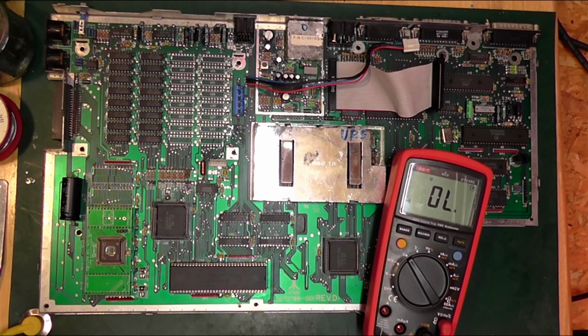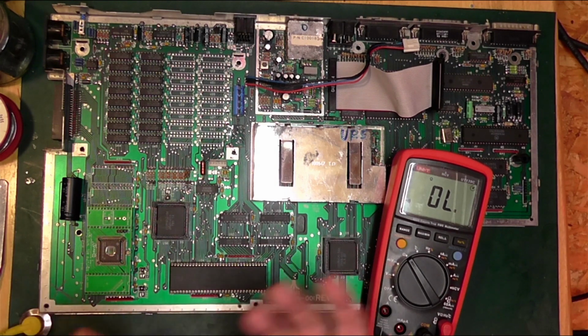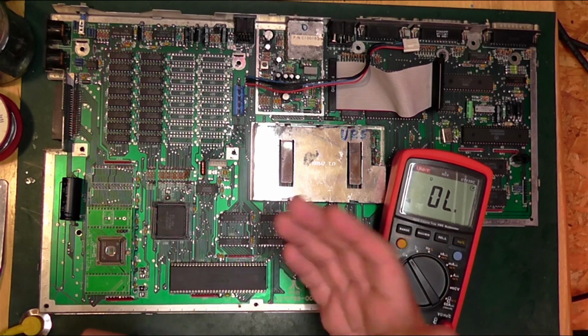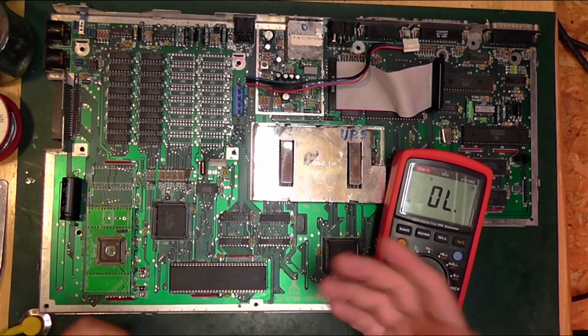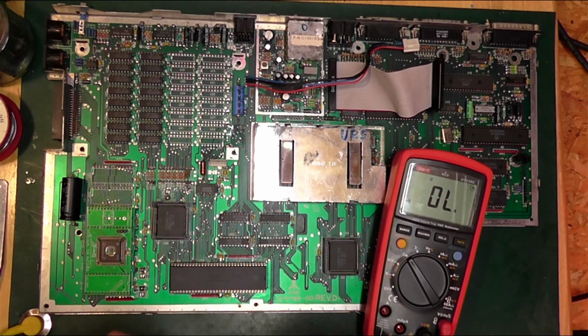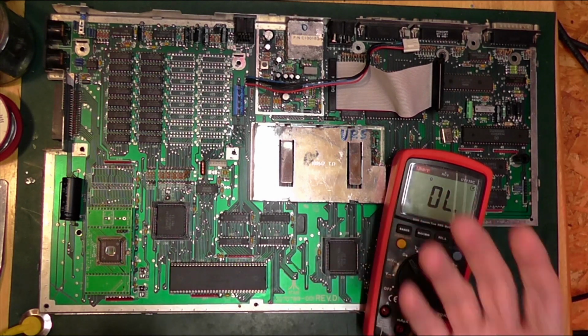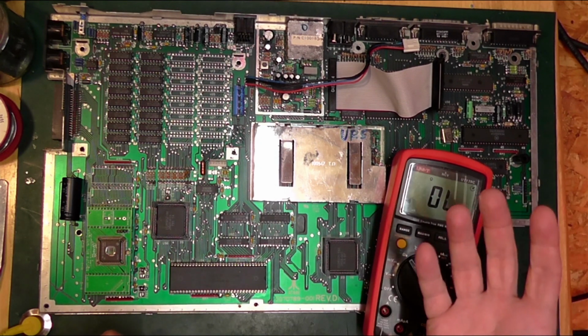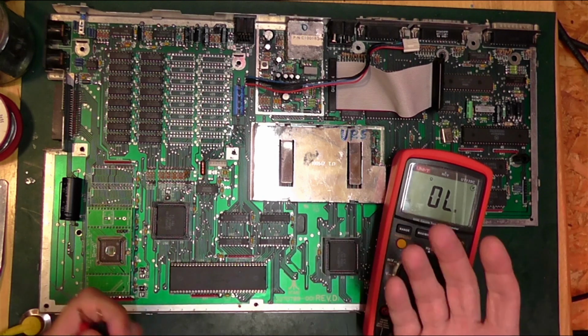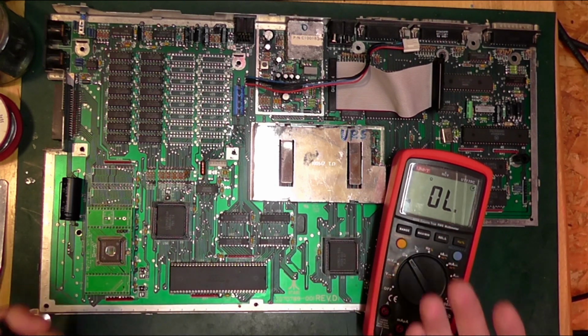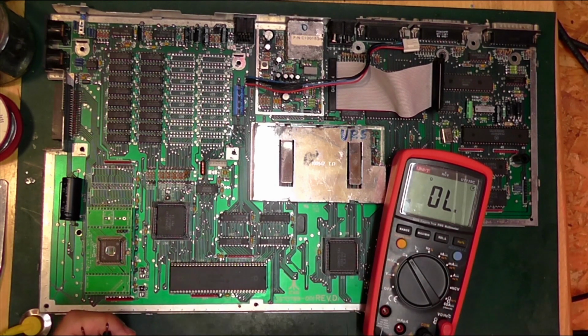They have to go from ground to, off to on, basically, which is ground to 5 volts, very rapidly. This is an 8 megahertz machine, so it's all relative. But in this case, within a clock cycle, well, half a clock cycle, it'll be about 62 nanoseconds, up and down, up and down, up and down.